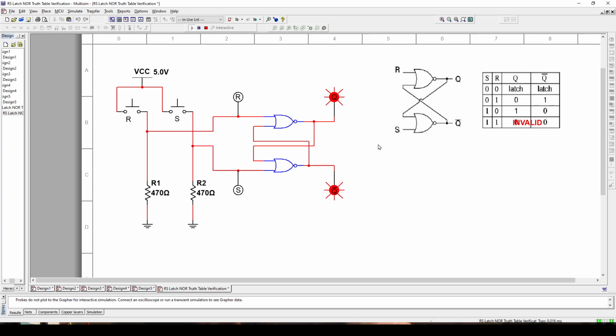So if you make two OR gates or two NOR gates or two whatever, they are not going to be the same. They're going to have slightly different propagation delays inside them. So one of them is going to race faster than the other, and the situation is going to settle down right away. Now, this is just too ideal. It's a software-based system. Okay, so basically that's what it is. Now, the little reflection is that this whole situation that we can create here with pressing R and S and latching into Q or not Q happens because